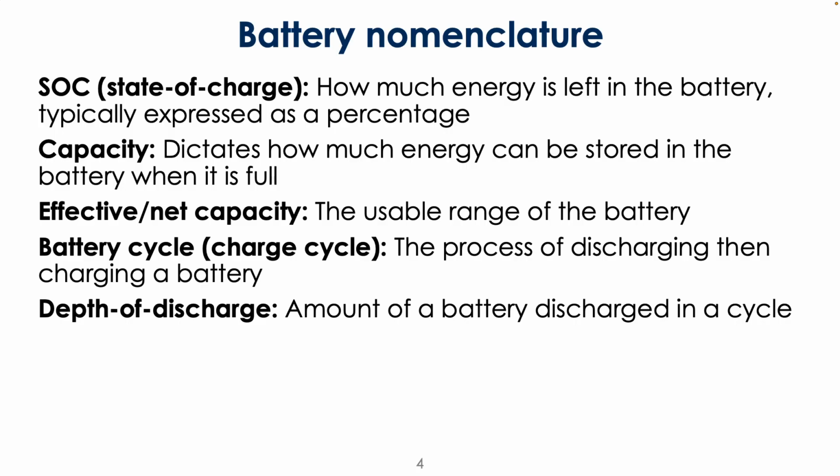One of the things we'll talk about is battery degradation, which is a loss in sort of capacity over time. If you are fully charging the battery and fully discharging the battery, you will degrade your battery faster. You can think of this like on the anode and cathode, you're putting so much sort of pressure on the battery that it starts to essentially degrade, lose the ability to hold on to ions. And likewise, if it's all the way empty, it can be hard to get it to start charging again.